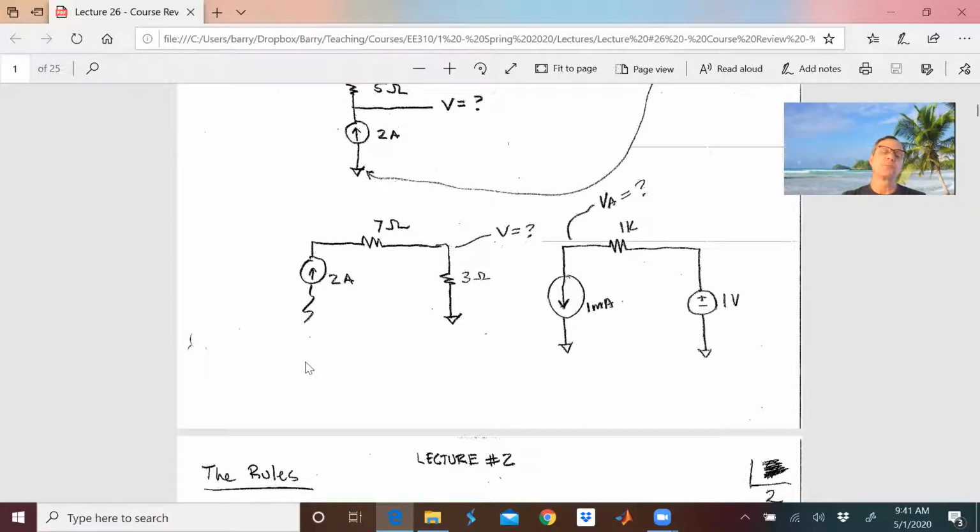Start at 0. Go down 2 amps times a mega ohm, and I get about -2 million volts right here, don't I? Because KVL on the fly, start at 0, because this end of the eraser is grounded, and it looks like a 1 mega ohm resistor. So from 0, I go down 2 amps times 1 mega ohm. I have -2 million volts right here, but I still have 6 volts right here.